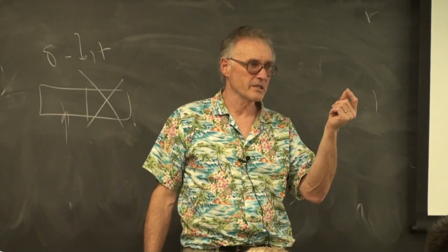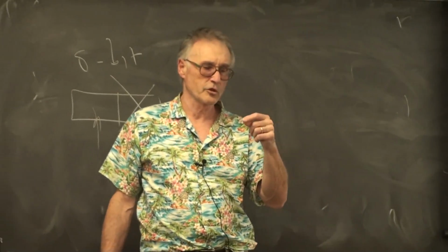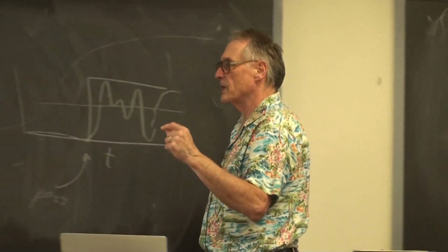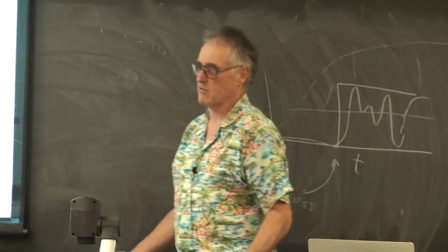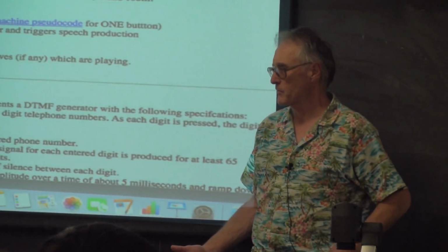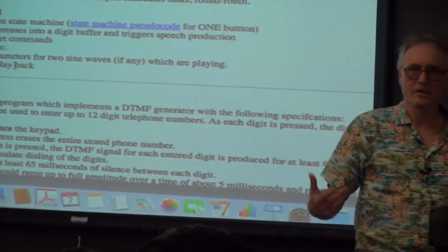So 100 milliseconds is enough resolution. You want a little bit better resolution than that. But certainly you don't have to have microsecond resolution like the CPU can do. You want tens of milliseconds of resolution, which means you're going to run the state machine about 30 millisecond rate.